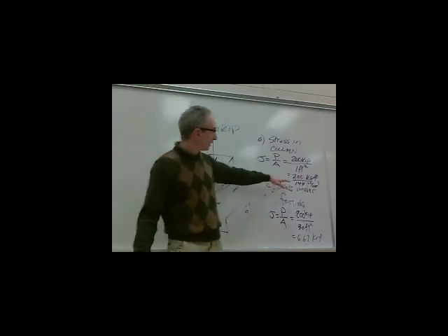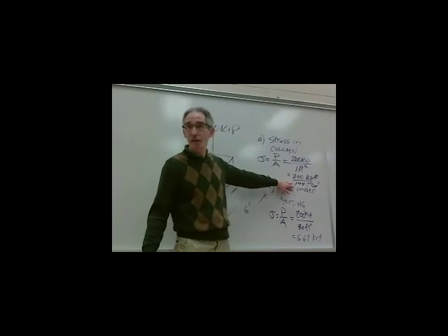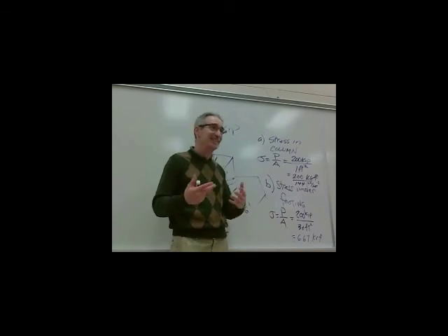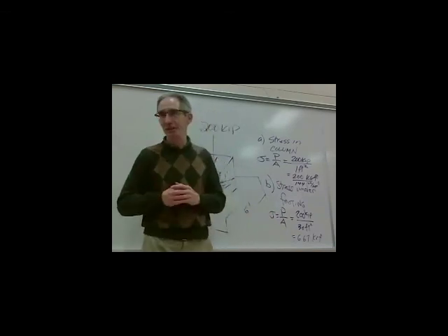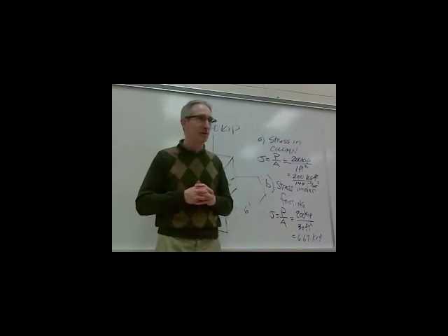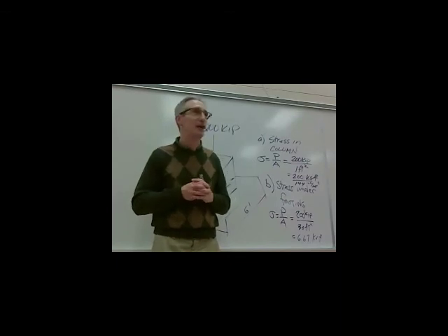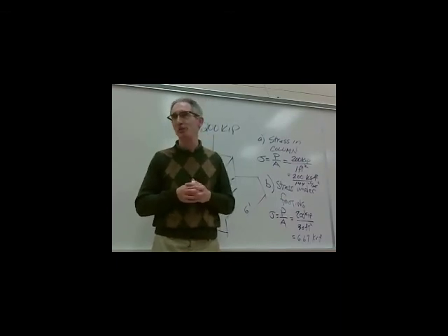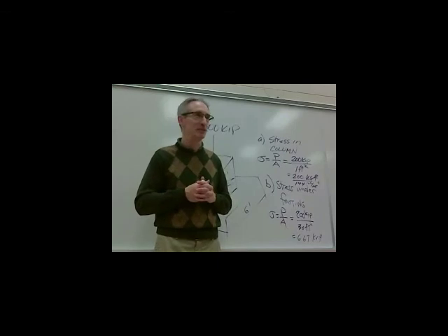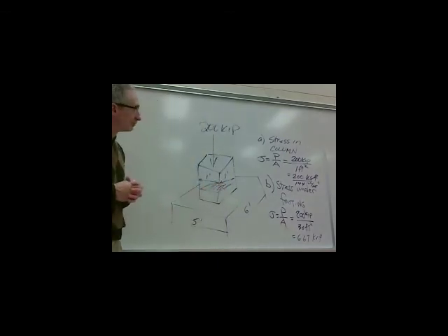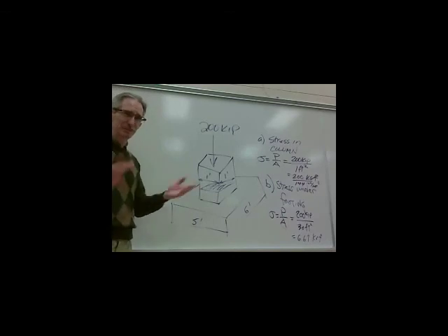So if this is, you said 1.39 kips per square inch. Yeah. If this was steel, or if this even was concrete, that's not that much. I mean, steel, it's hardly anything. Concrete, most of our concrete, we'd say, is 4,000 pounds per square inch, or 4 kips per square inch, under compressive stresses. All right? So, you get sort of the concept there.